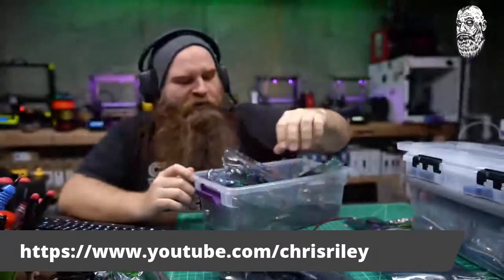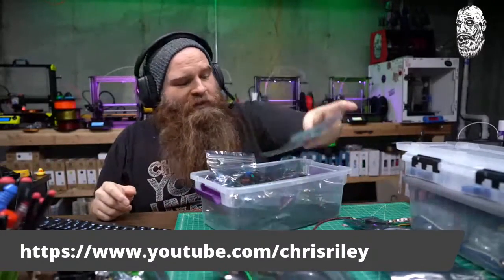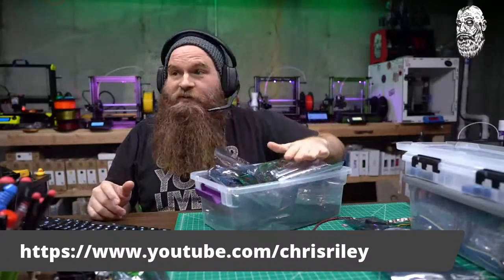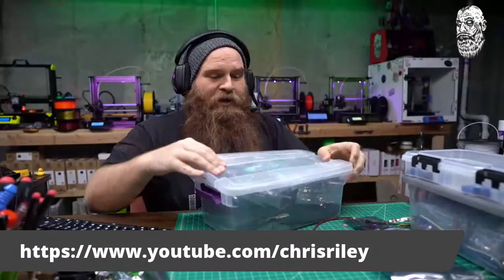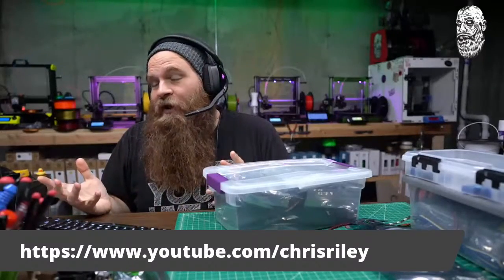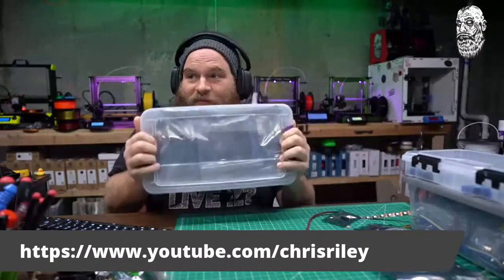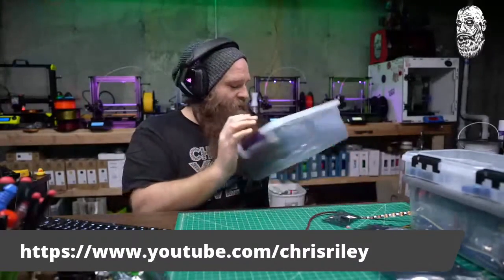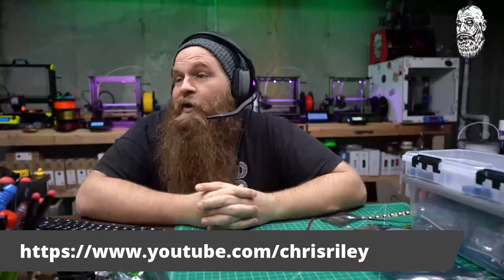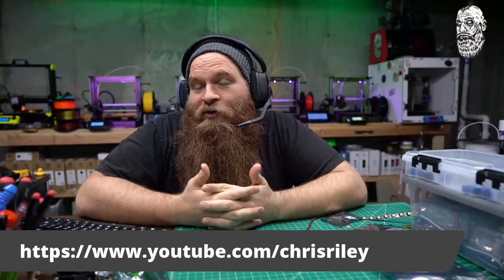You need to know what board you're working with, because if you don't, it makes things a lot more difficult. One of my favorite boards, and one that's easy for me to understand so I don't lose my place too often, is the SKR 1.4. It's the big popular board, but just make sure you know your board. If you're working on a CR10 or Ender 3, they all have Melzi boards, so that's pretty easy. Step one, pick the board you're going to be working with. Either ask someone online, like, what does my Ender 3 have? What does my Chiron have? What does my Prusa Mark III have? Just find out what board you're going to work with.